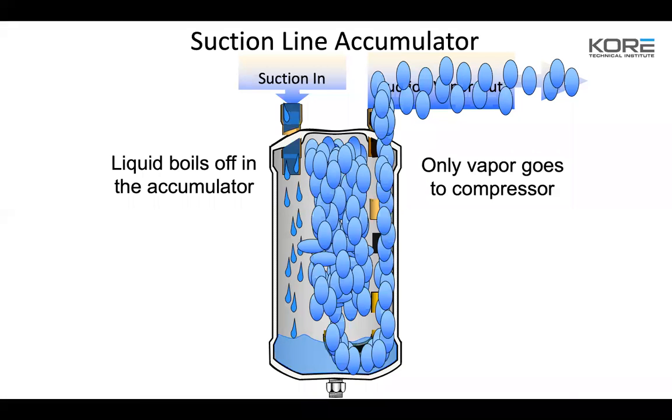We've seen that twice on those 0-zone cases, just in the last year. And we have heat exchangers on here, so we'll talk about that when we get to that. But yeah, if you have an excessive flooding problem, always go after what's downstream. It's not boiling off the liquid soon enough, because remember, we want to hit that superheat at the evaporator. That's telling us how much heat transfer is happening at the evaporator.